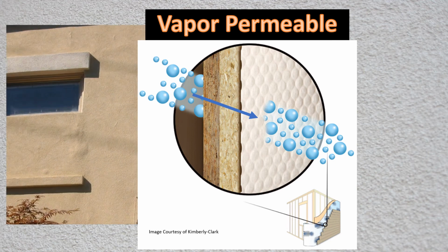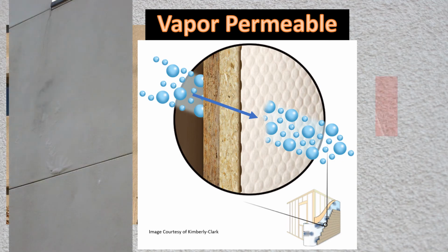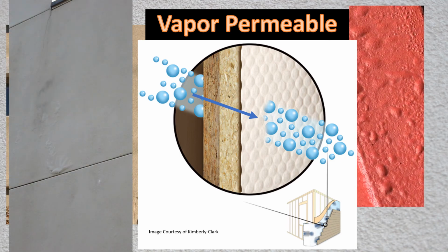When water cannot escape through the finish coat, it will tend to blister or bubble the finish off of the base coat. The same can be said of paint coatings. Painting cement with an elastomeric coating can result in blisters when the moisture tries to escape through that non-vapor-permeable coating. This is why the SMA recommends vapor permeable coatings for all cement base coats.